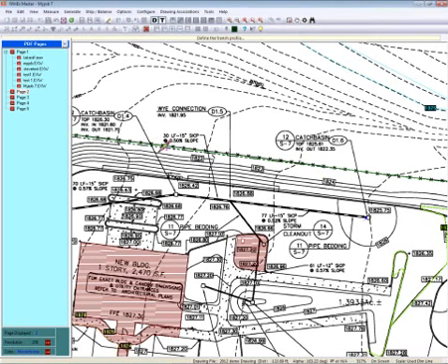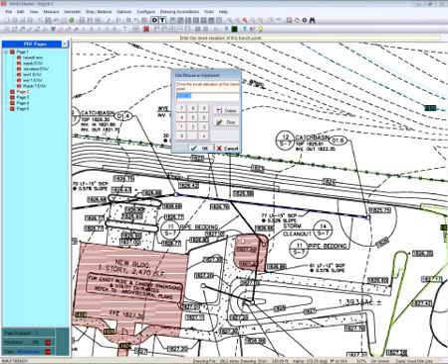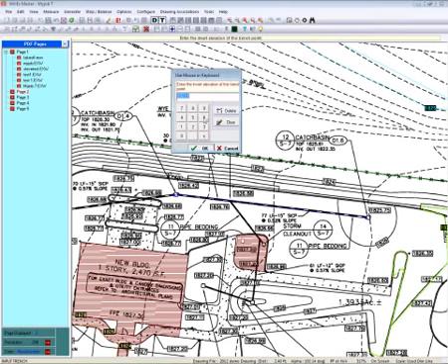By the way, you can choose by entering your numbers on the pipe by the invert, the middle of the pipe, or the top of the pipe. I have it set default for the invert. And here I'm coming in at, let's see, at 1821.80. I won't bother doing this whole thing, but I think you get the drift of how we do it. And I'm going out at 1821.70.